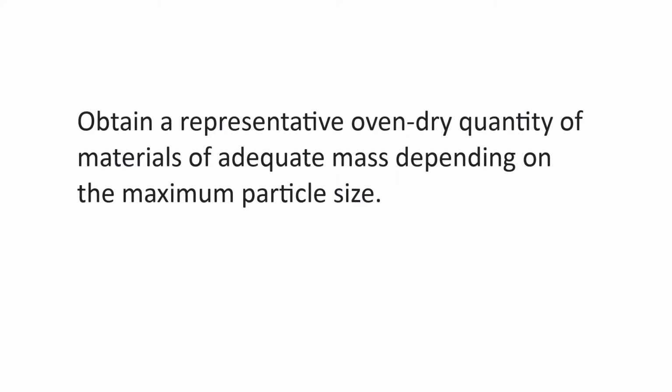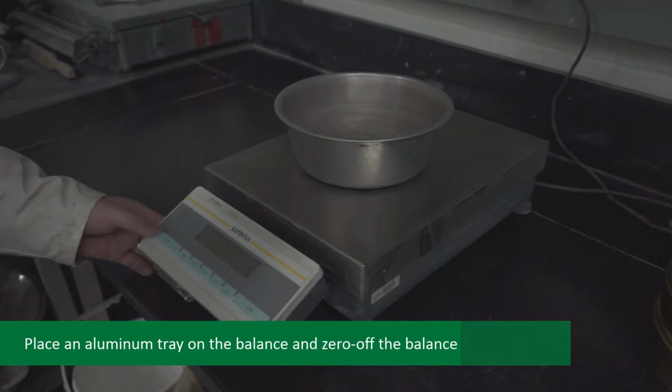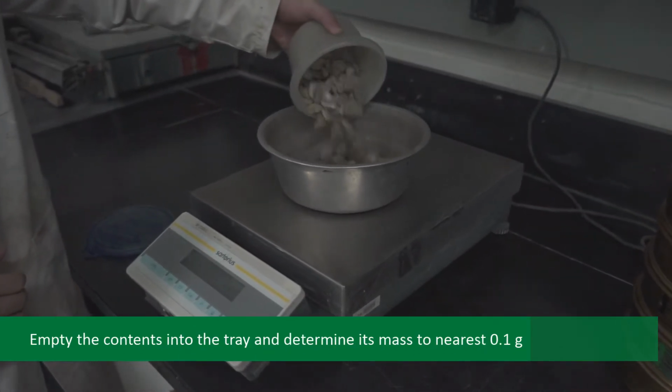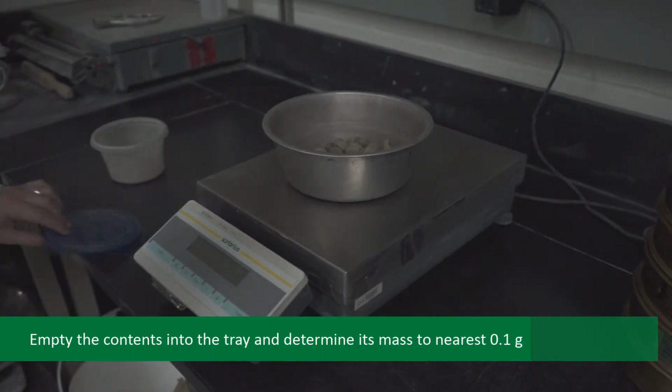In order to begin, first obtain a representative oven-dry quantity of material of adequate mass depending on the maximum particle size. A suggested sample size is 250 grams for concrete sand and between 650 and 750 grams for gravel. Next, obtain an aluminum tray, place it on the balance, and zero off the balance. Empty the contents into the tray and determine its mass to the nearest tenth of a gram.